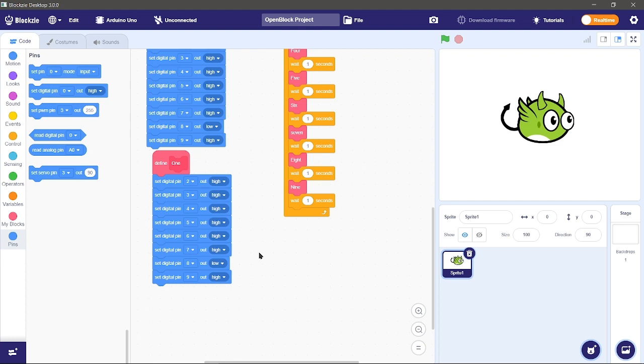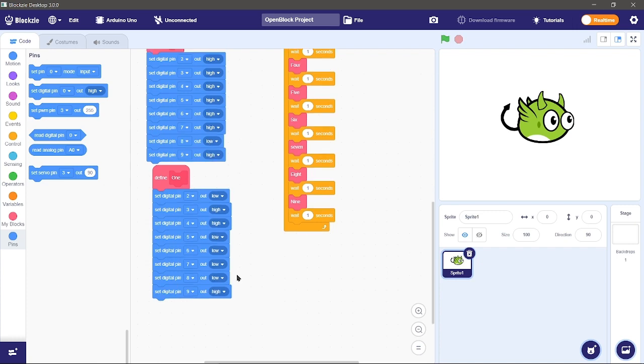So the pin number for 2, or digit number 1, is 2 in low, 3 again high, 4 low, 3 and 4 only in high, all the others in low. Now the pin number 9 here is connected to the dot point, and that particular point is going to turn on, hence we are making it high always.